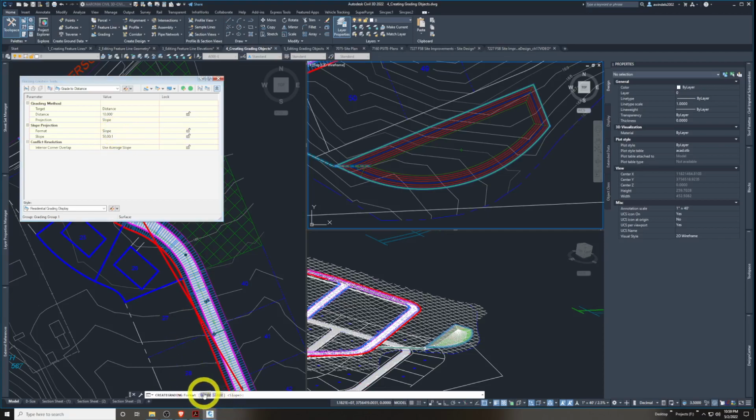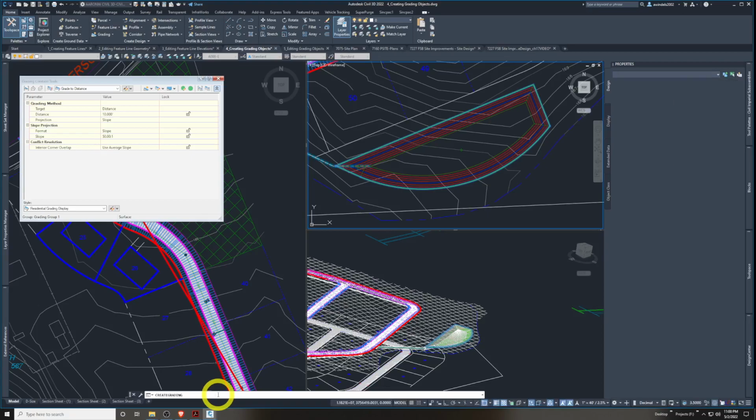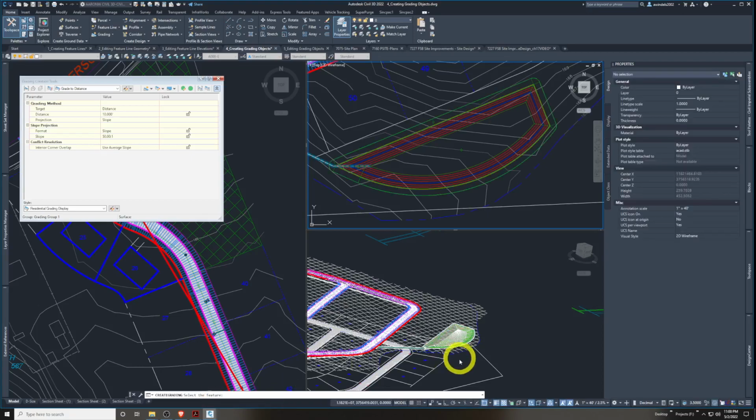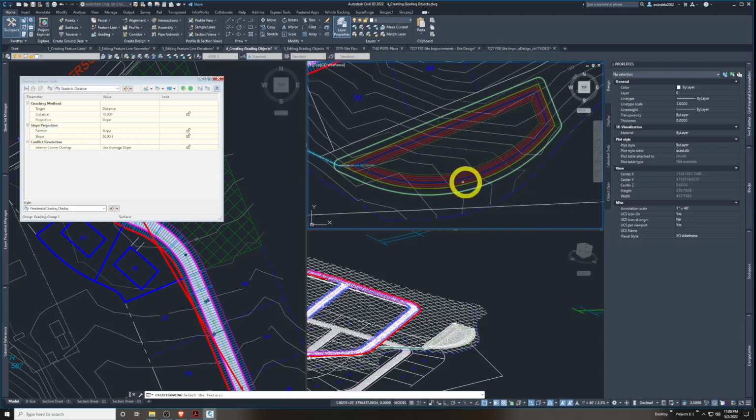Instead of doing slope, let's click grade, or you can click G for grade. But I prefer just to click the button, the grade out button. And in this case, we'll accept the default grade of 2%. This grades uphill at 2% in uphill fashion. Hit enter again, and it made another grading out. So it graded out even further, 10 feet at 2%, 10 feet horizontally. Basically, we just essentially made the big berm around this pond.